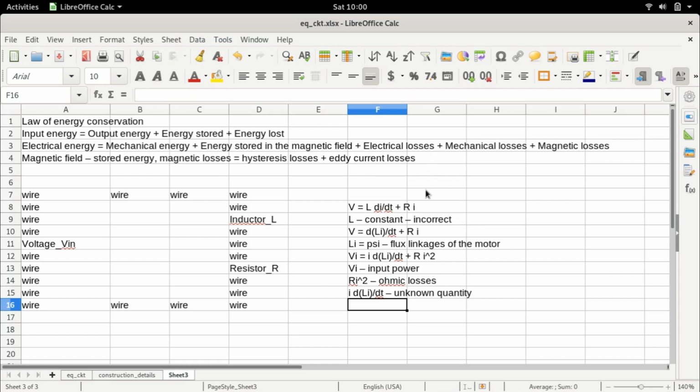In many cases, we can represent this resistance here, and we can also choose stator and rotor resistances in such a way that they bring in the mechanical and magnetic losses to some extent. It is possible. So it appears as if this last part of the equation can be accounted for by these ohmic losses, that is I squared R.